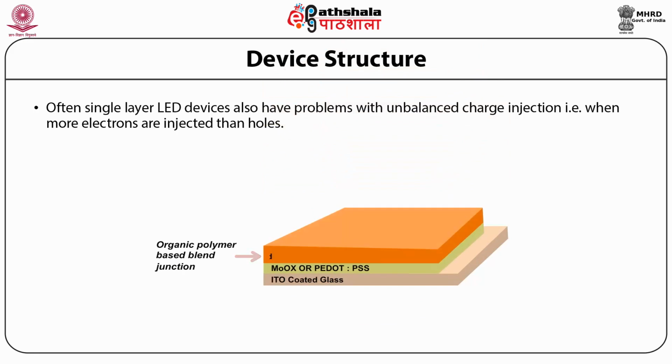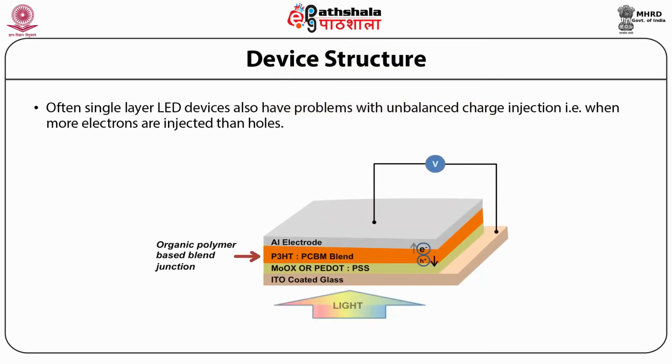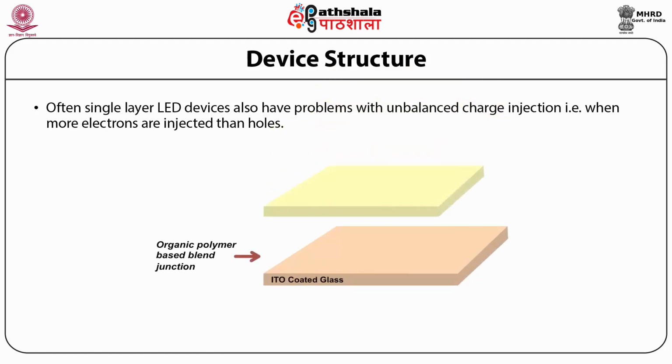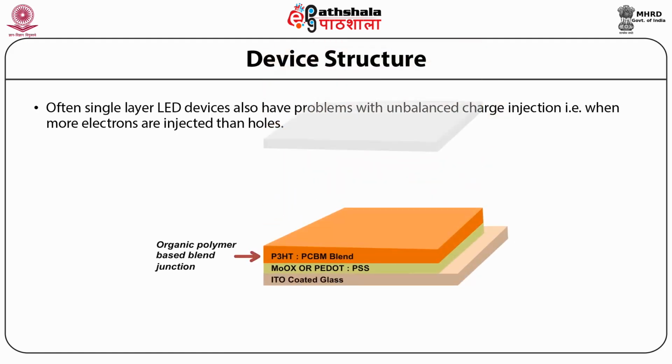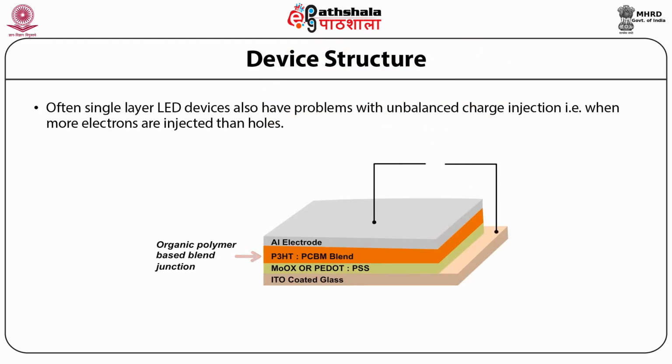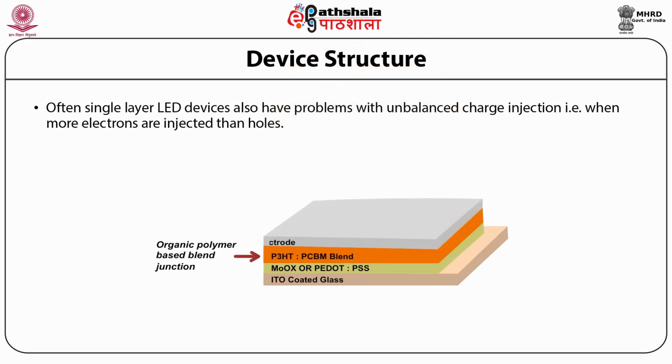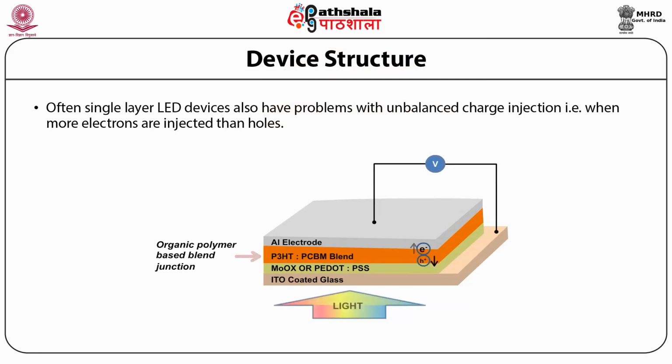Exciton dissociation is generally brought about at regions of high electric field, such as interfaces like the organic-organic interface or metal-organic junction. It is because of this lack of exciton dissociation sites that single-layer organic solar cells have an inherently low efficiency.